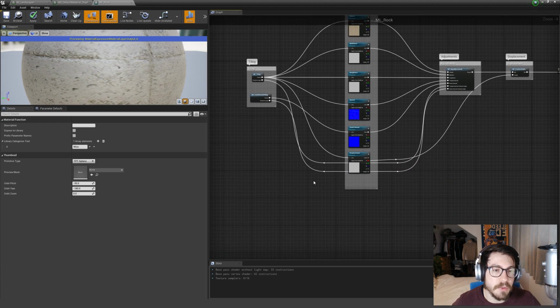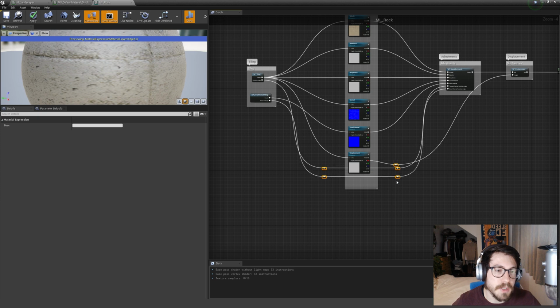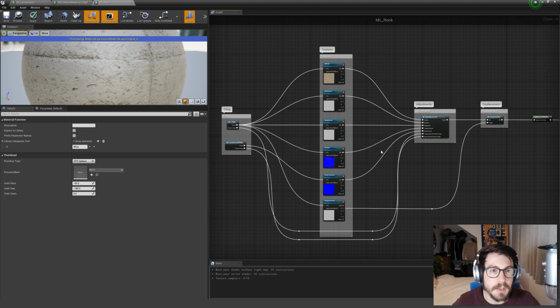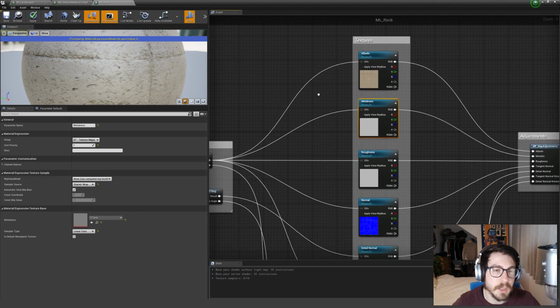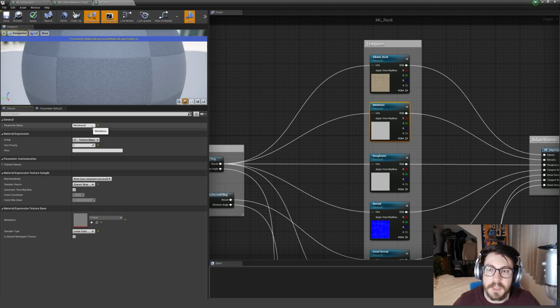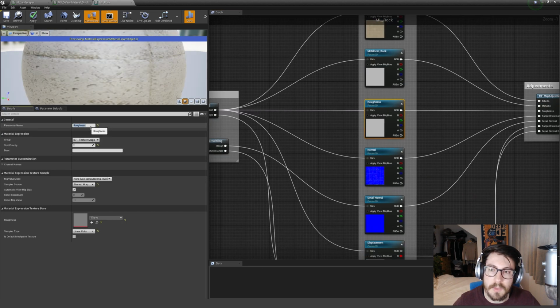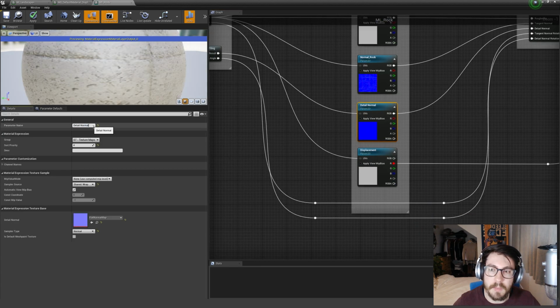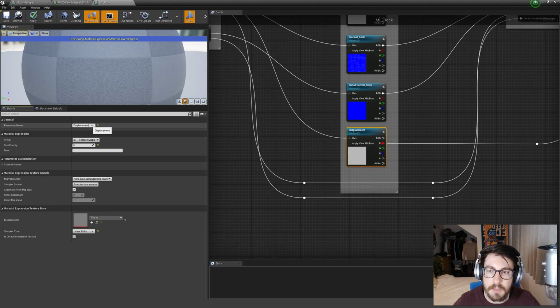One thing that we want to do before that though is to rename all of the parameters that we're getting here to something that is more usable in the material instance, because right now they are all called albedo, metalness and so on. If you would use that multiple times, it would confuse the system, and we cannot add multiple textures. So we need to rename this to something that makes sense. For example, _rock behind all of these. And then we're going to put it into a different group as well, once we are done with adding this name here, so that just in the material instance it's a bit more manageable to actually use that one.